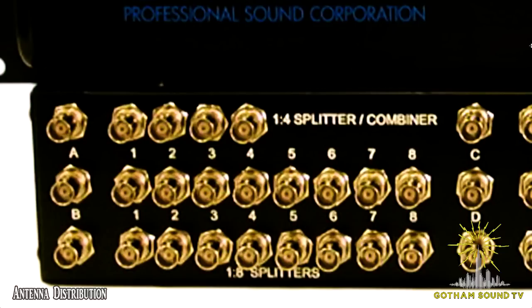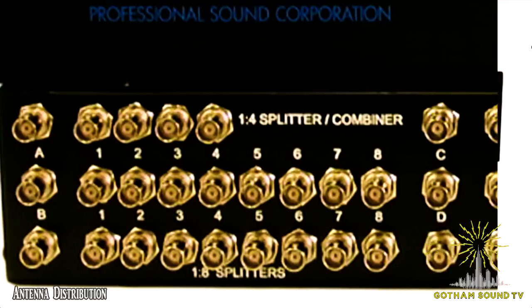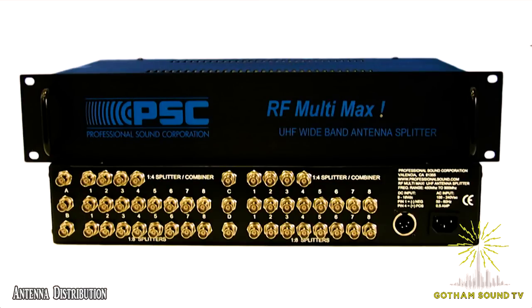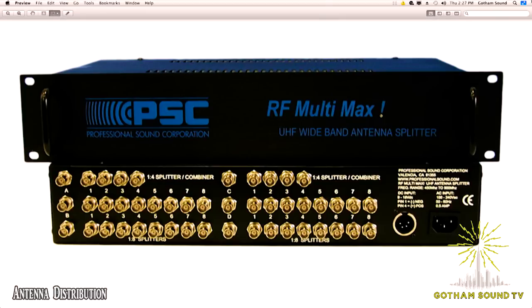And then we don't have a close-up of the right, but if we go to the full picture, splitting to the other side, all of my 2s, C2, A2, and there is no B2, would get hooked up to the right-hand side of this combiner. Oh, by the way, every unterminated input or output would get a 50 ohm terminator on it. It's just best practice.